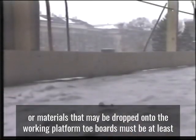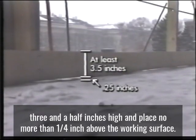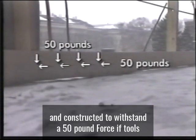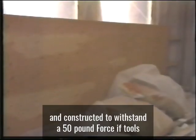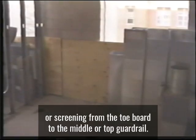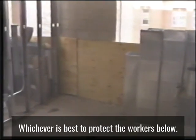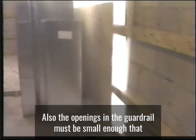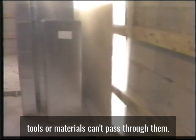Toe boards must be at least 3.5 inches high and placed no more than 1/4 inch above the working surface. In addition, they must be designed and constructed to withstand a 50-pound force. If tools or materials are piled higher than the toe board, add paneling or screening from the toe board to the middle or top guardrail, whichever is best, to protect the workers below. Also, the openings in the guardrail must be small enough that tools or materials can't pass through them.